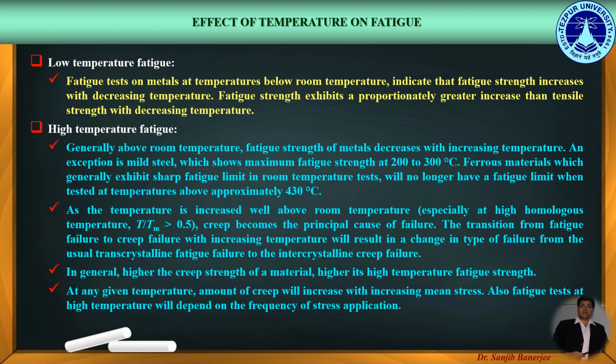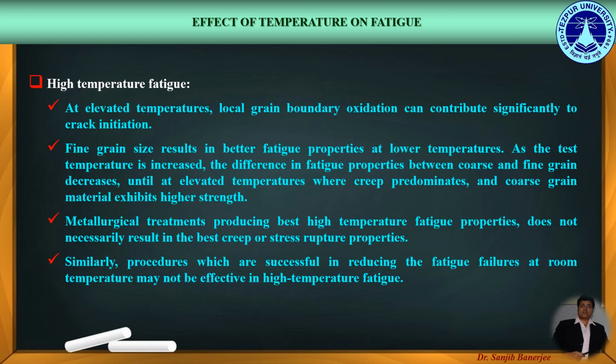At any given temperature, amount of creep will increase with increasing mean stress. Also, fatigue test at high temperature will depend on the frequency of stress application as well. Continuing with the high temperature fatigue, at elevated temperatures, local grain boundary oxidation can contribute significantly to crack initiation.